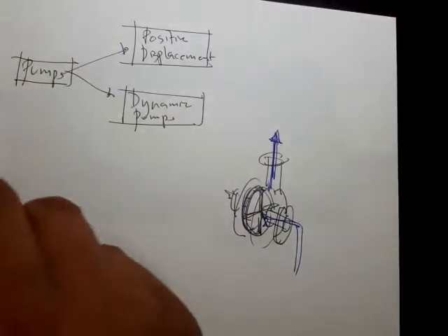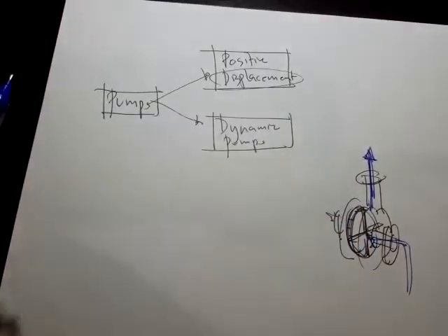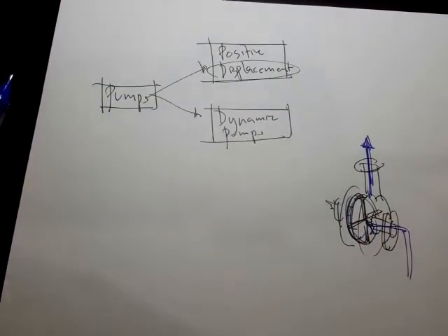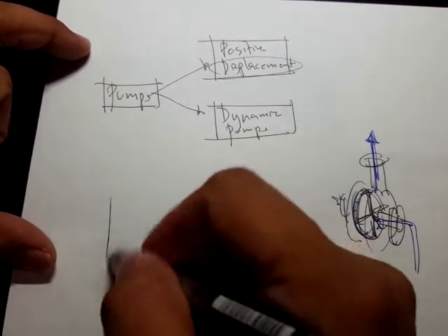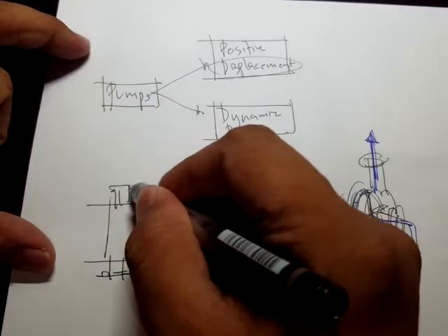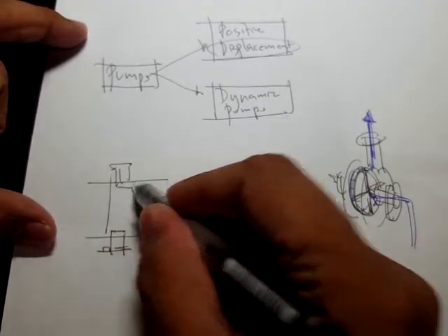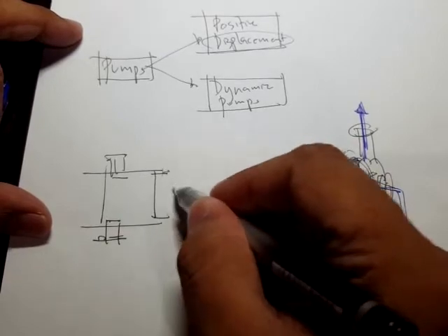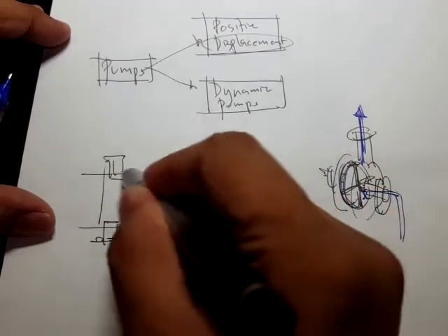So in that way, of course, it's going to be related to increasing the energy. Whereas with positive displacement pumps, from the word displacement, the intention is actually to displace some volume of fluid, and thereby in that displacement of fluid, there's going to be some increase in the energy. So a typical example is this piston pump. Right, so we have this inlet side and we have this suction side, and of course there are going to be valves right here, and there must be some pistons that are oscillating, or sorry, reciprocating, right? So there must be some piston, right?